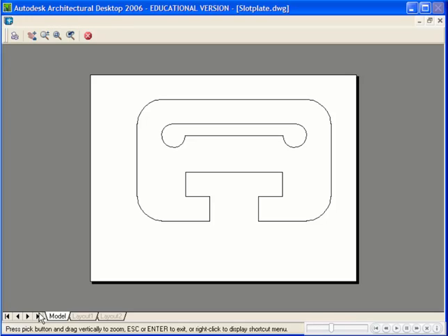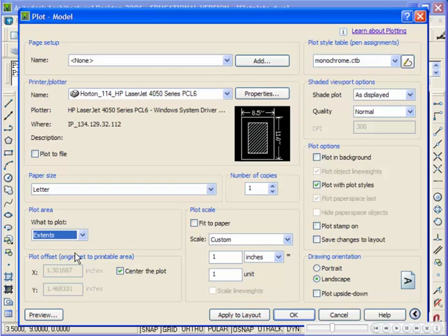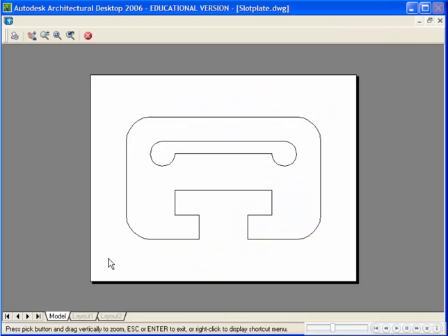To center something exactly, when you have an item like this here, it's probably better to use extents. So I'm going to right-click Exit, and I'm going to print extents. Now, it should be perfectly centered. I go to Preview, and yes, it is perfectly centered.